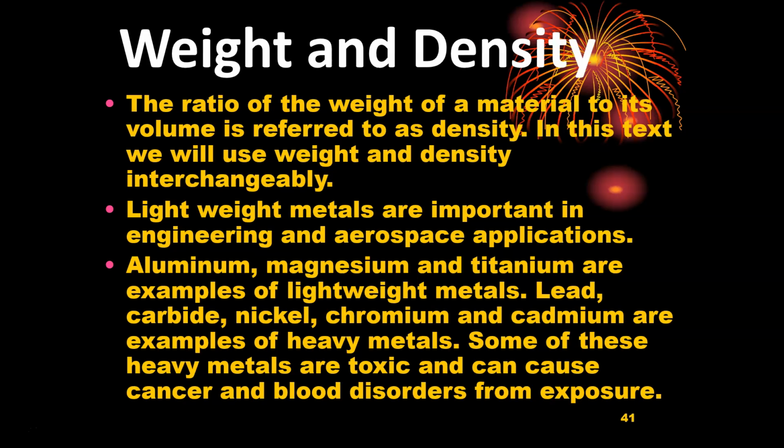Some of these heavy metals are toxic and can cause cancer and blood disorders from exposure. You got to be careful. Beryllium copper is safe to machine, but if you grind it or put it on a sander, the dust is carcinogenic. Figure 428 shows the density of common metals in pounds per cubic foot.